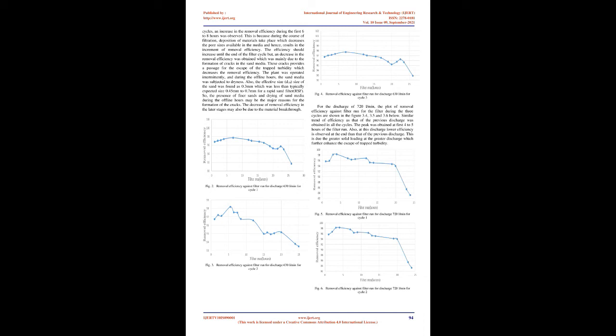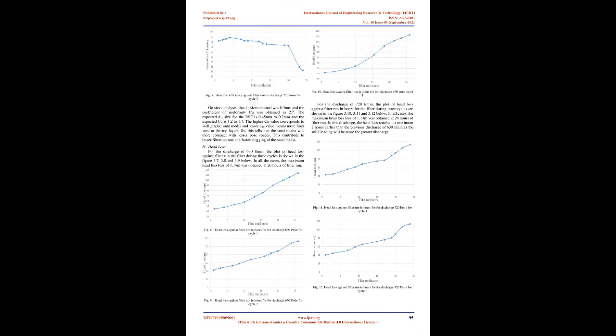Clear water reservoir. An underground RCC reservoir has been constructed for the storage of the treated water. The shape of the reservoir is circular and its roof is dome-shaped. The volume of the reservoir has been worked out on the basis of the water consumption pattern recommended for small towns of Nepal. The capacity of the reservoir is taken as 500 cubic meter with a radius of 6.6 m. The water reserve to be used in case of emergency like firing has not been taken into consideration.